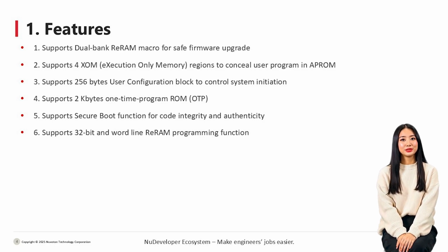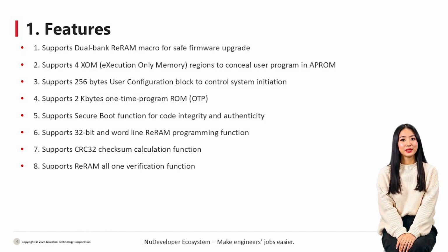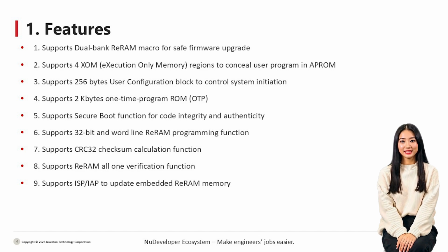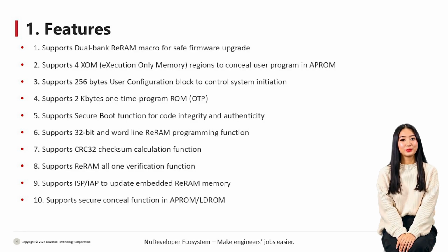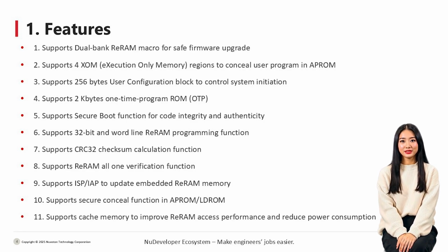6. Supports 32-bit and word-line ReRAM programming function. 7. Supports CRC32 checksum calculation function. 8. Supports ReRAM all-one verification function. 9. Supports ISP and IAP to update embedded ReRAM memory. 10. Supports secure conceal function in APROM or LD-ROM. 11. Supports cache memory to improve ReRAM access performance and reduce power consumption.